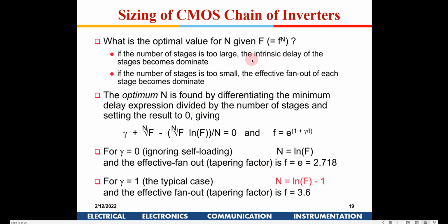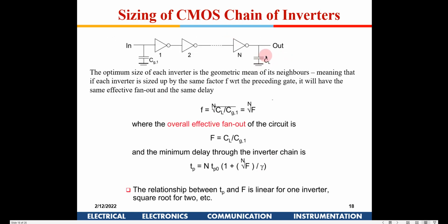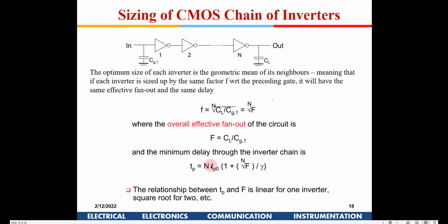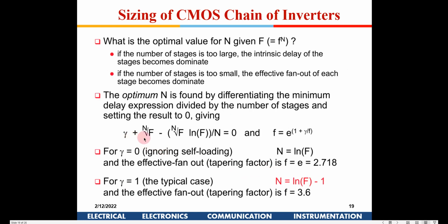Now if you see here, what should be the value of n? This we know, this comes from the load requirement, and this is the inverter gate capacitance. What is variable out here is n, how many transistors we should have. So I differentiate this equation with respect to n. The only variable out here is capital N, where all other things are constant.